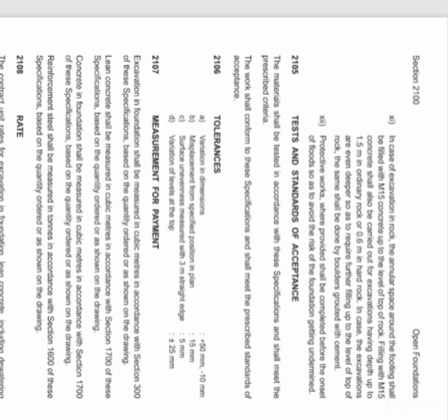Measurement for payment. Excavation in foundation shall be measured in cubic meter in accordance with section 300 of the specification based on the quantity ordered as shown on the drawing. Lean concrete shall be measured in cubic meter in accordance with section 1700 of the specification based on the quantity ordered or as shown on the drawing. Concrete in foundation shall be measured in cubic meter in accordance with section 1700 of the specification based on the quantity ordered as shown in the drawing.